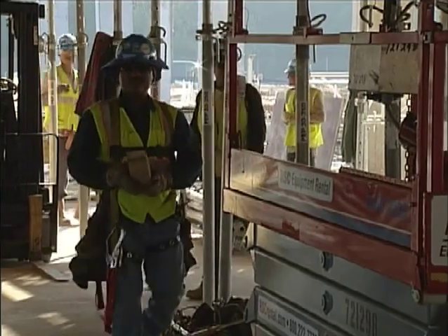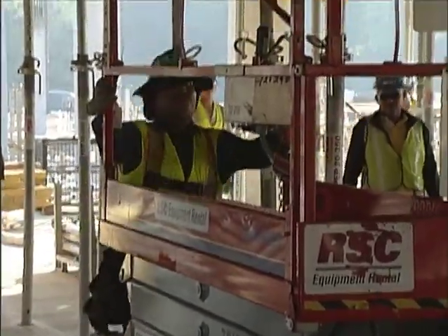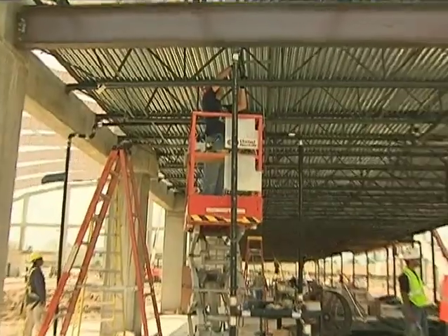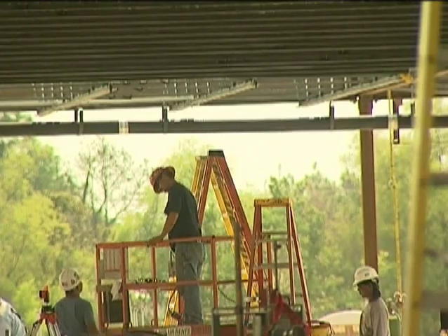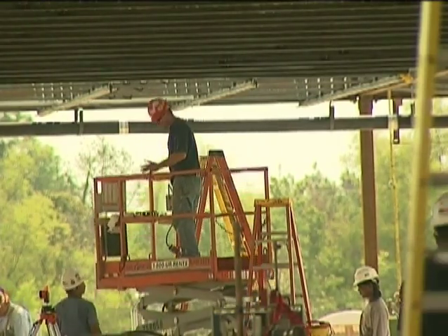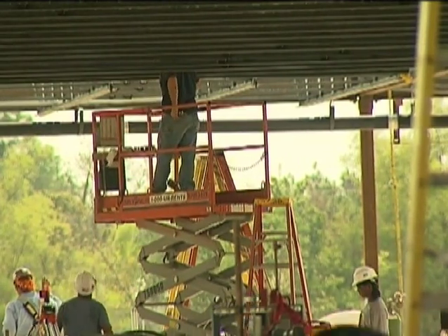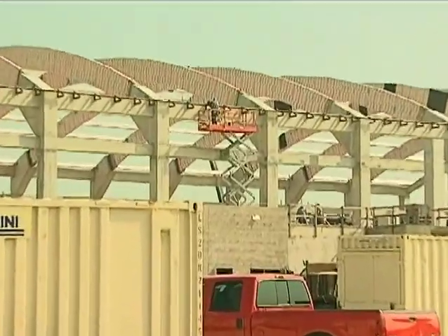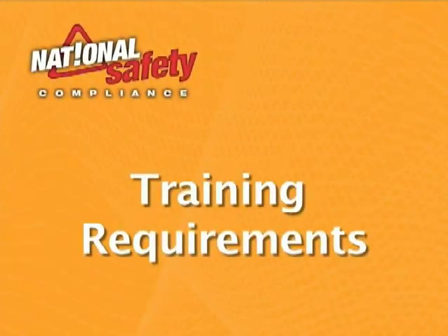Scissor lifts are another common type of aerial working platform. The lift works much like a pair of scissors. The parts that elevate the platform contain crossing, interlocking members. When pressure is applied to the outside of the lowest set of supports through hydraulic, pneumatic, or mechanical means, the crossing supports lengthen to raise the platform. Scissor lifts usually cannot reach as high as a boom, although some may reach up to 40 or 50 feet high.